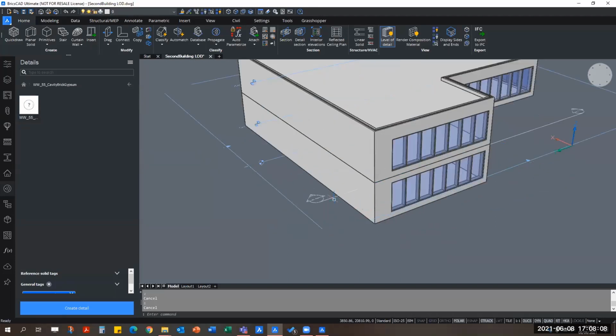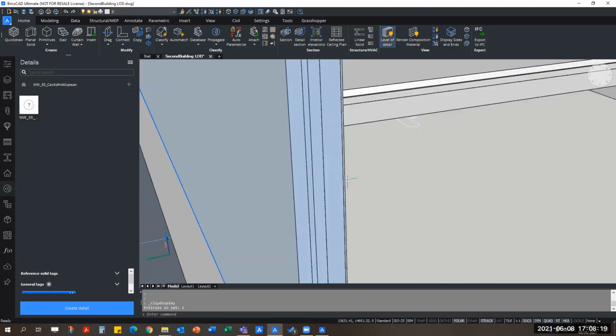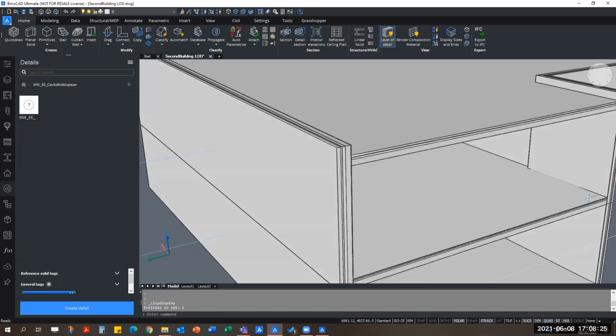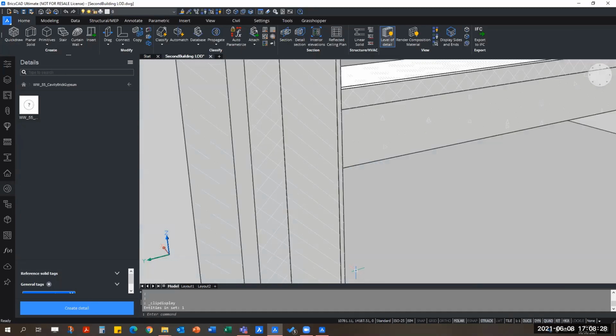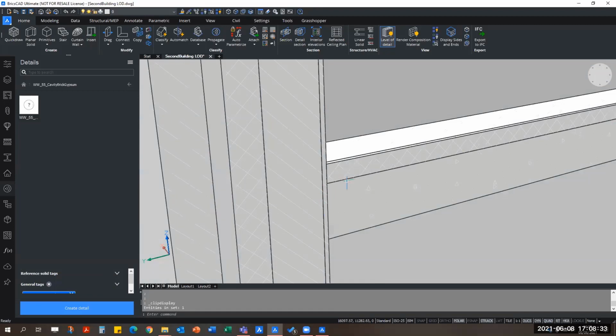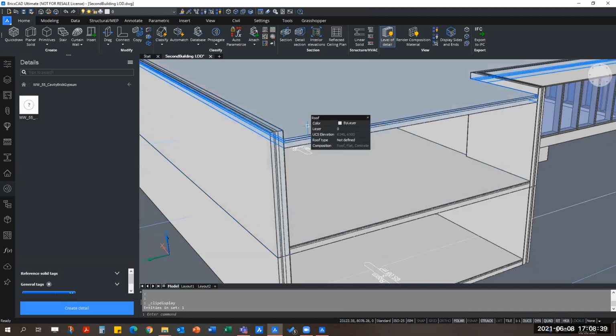And over here, you will notice there is a section pane already created for you. And all you have to do is go on to click. And you will notice that there are some bits and pieces. If you're familiar with construction, you'll notice that there are some of the joints that don't really make sense because you have a gypsum plasterboard running down here, whereas the structures are not connecting. So again, what we're going to do is create a detail to address this issue and then propagate it throughout this building. So you only do it once and correctly.